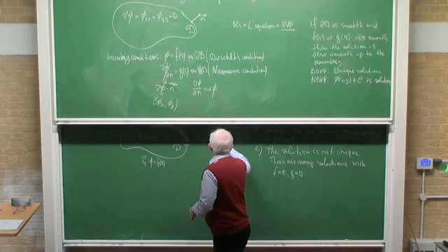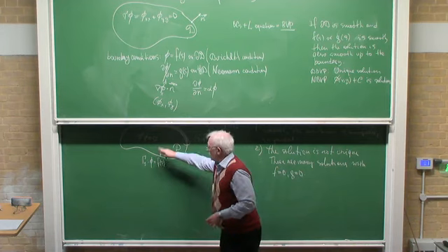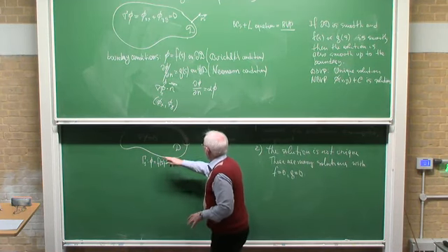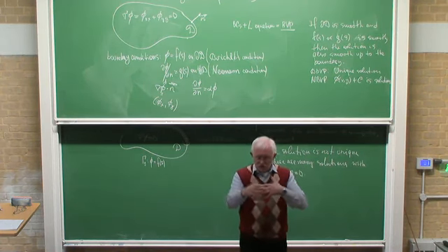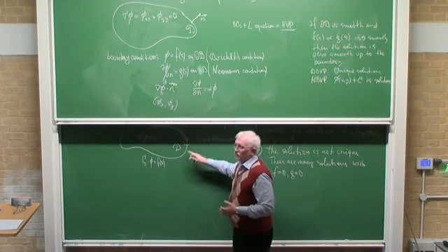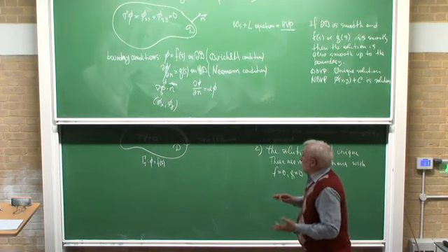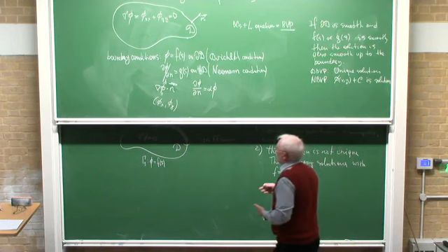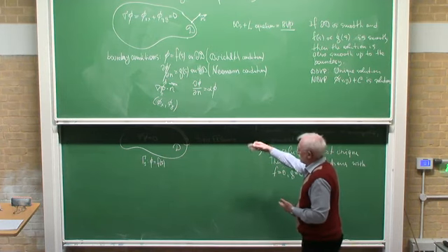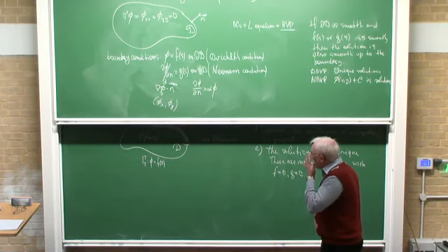Super finite elements are different from the elements you use as approximation inside the region and on the rest of the boundary. Close to the point where the boundary condition changes type, the super finite elements account for that singularity. They use special functions, in particular that square root of the distance, to approximate the solution with unknown coefficients which are determined by assembling all those finite elements.